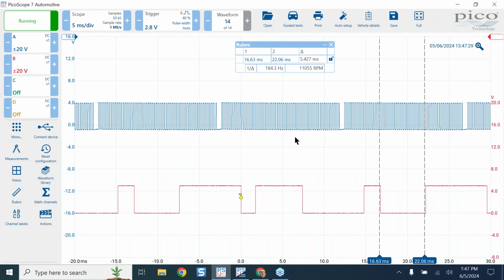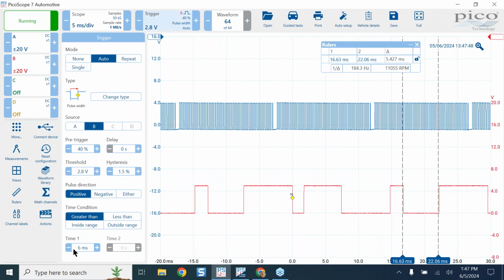Turn scope back on. Now, using the measurement that I made on the medium width tooth, I've synced on the wide tooth because I know that I have to be greater than this, and I can probably break that pretty fast. I can probably go in and go to 5 or maybe 4 and break that pretty fast, just proving that I synced it properly, and it wasn't just because I was pushing buttons and wasn't quite making my measurements or wasn't measuring them at all.